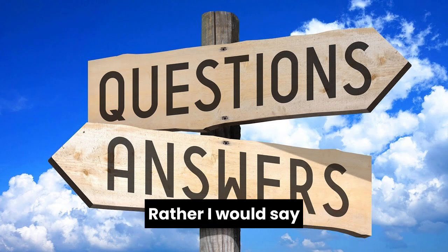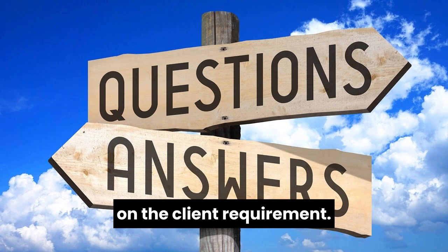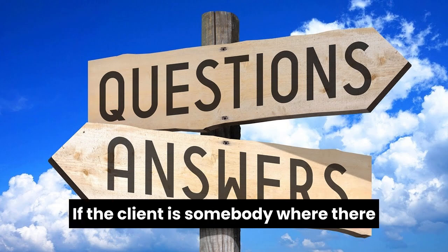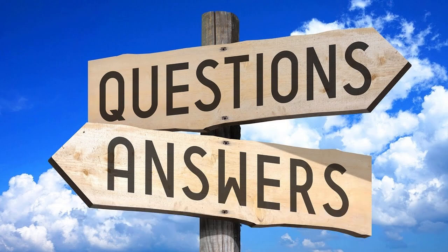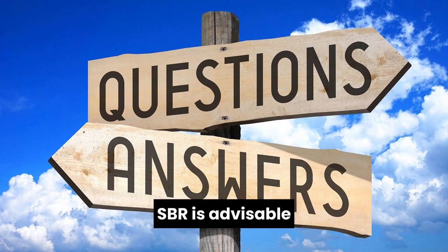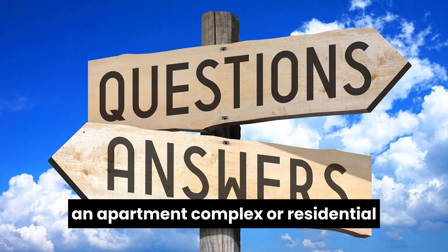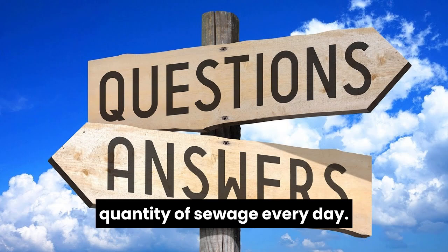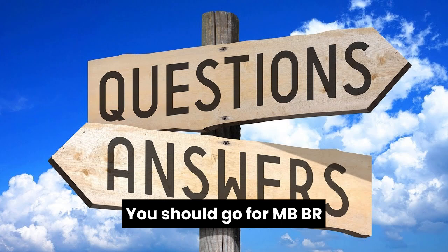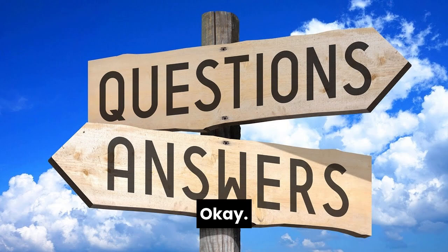Rather, I would say how we should select or suggest MBBR or SBR is based on the client requirement. If the client is somebody where there is no standard load, that means there is no constant load, something like a hotel, hospital, educational institution, there SBR is advisable. If it is a constant load, like an apartment complex or residential project where you are getting more or less plus or minus 5% the same quantity of sewage every day, you should go for MBBR with your eyes closed. There should be no second thought. Okay, sir.